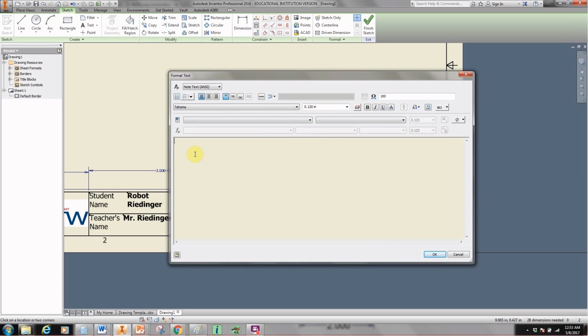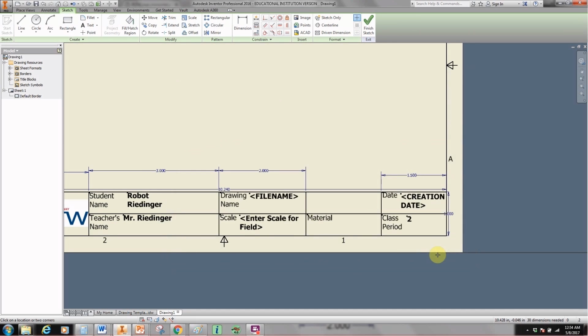In the final exam and other parts, you're going to be drawing and putting these drawing files, and it's going to ask and expect you to put what the material is in addition to scale. So you need to enter that. This again is another prompted entry, but instead of entering prompt, this is material. This way you'll know which one's which when these prompts come up. Again, we choose bold and we click OK.